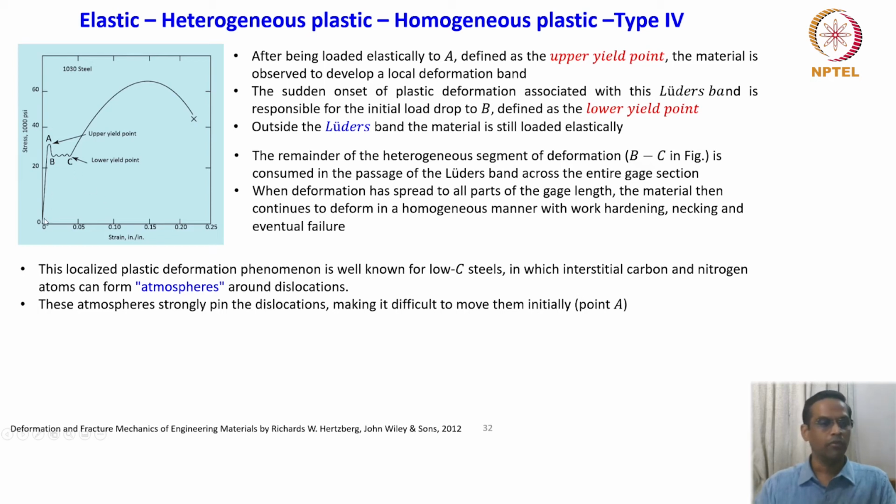That is, we are trying to explain at the point A. Okay, the stress keeps on increasing, and then at the point it just locked up. So at the point A, the dislocation and interstitial interaction is pretty strong, and the dislocation motion is restricted.